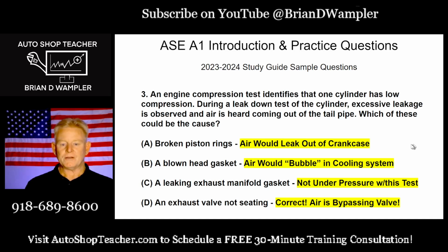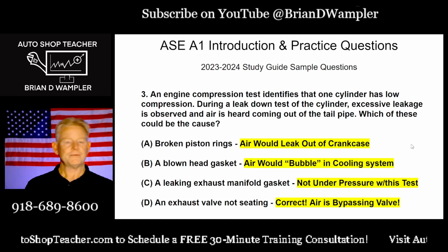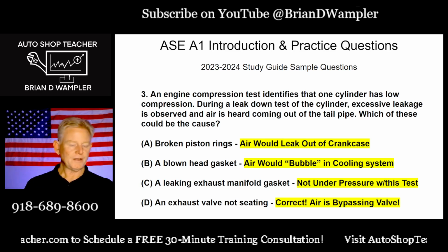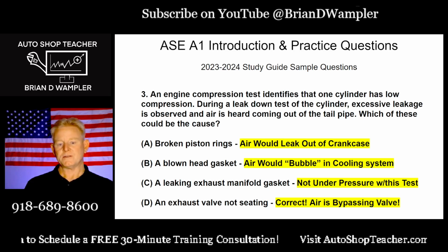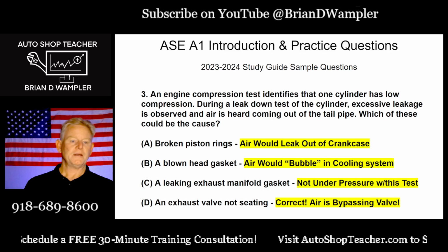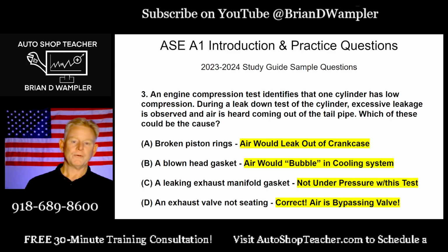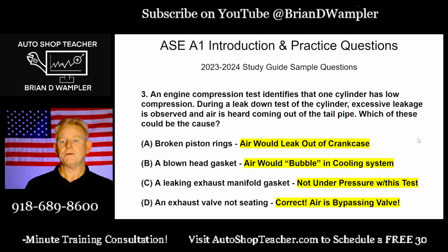Well, that is your correct answer, because air is bypassing the valve. So maybe we got a bad seat, a burned valve, bent stem, something to that effect. We have an exhaust valve that is not sealing. So the air that's being pressurized into the cylinder with the test equipment is going out through the exhaust, and that's why you can hear the air coming out of the tailpipe.